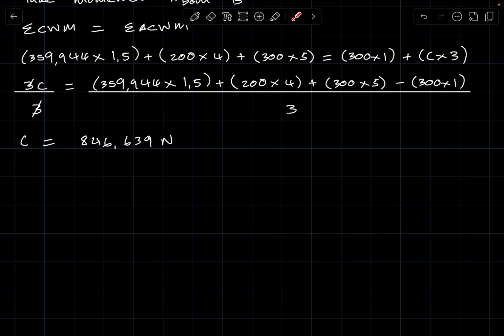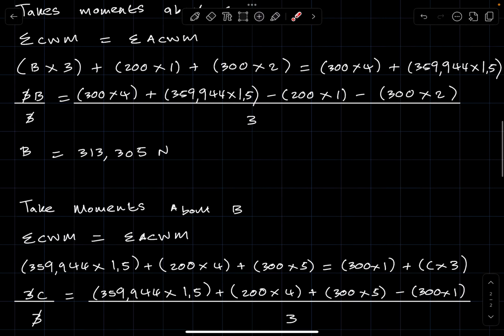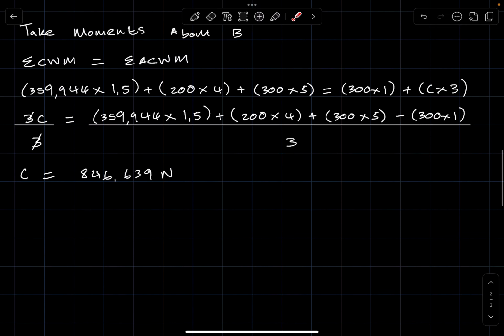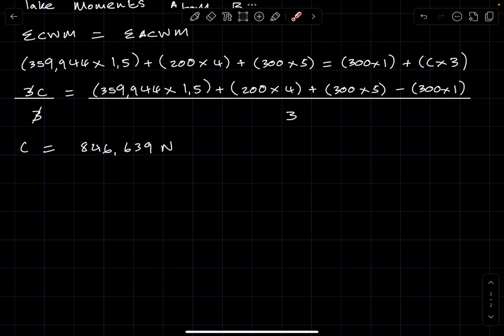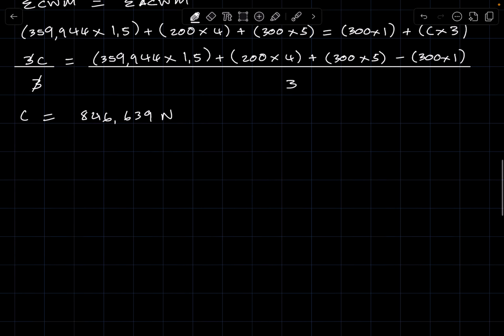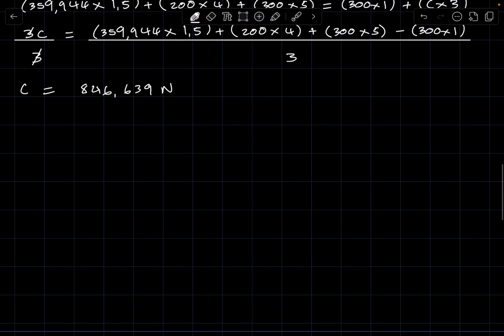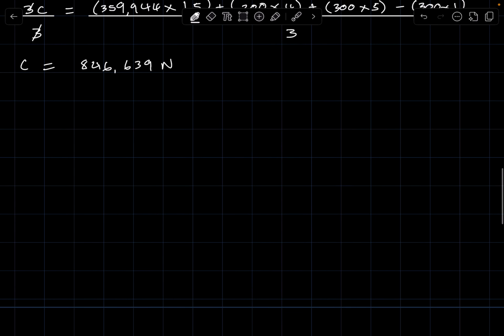Right, and that is how you would calculate the reactions. After having calculated the reactions, to prove that your beam is in static equilibrium, you then have to calculate the sum of forces along the y-axis, and they must be equal to 0. By that I mean, you say the sum of forces along the y-axis is equal to 0. This here is a condition of equilibrium.